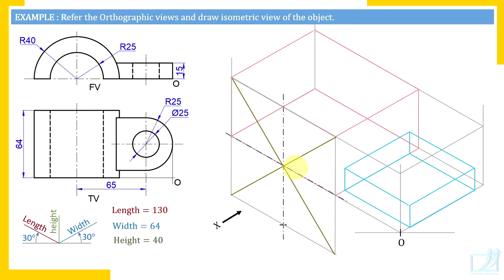These 4 centers, where are those 4 centers? You must be sure about them. So 2 centers to draw longer arcs, centers are in diagonally opposite quadrant. So if you want to draw arc here, center is here. And if you want to draw arc on this side, center is here. So ends of shorter diagonal are the 2 centers. And then you join one end of shorter diagonal, any one end, with midpoint of opposite edges. Then the intersection you get on the longer diagonal, those intersection points are the other 2 centers.